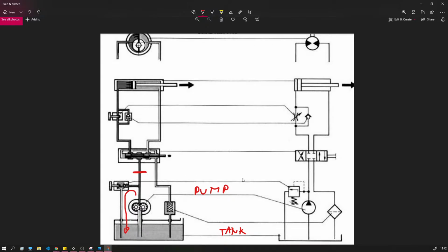So we have the relief valve here. If we have the pump that's giving us enough flow rate, and we have the set relief valve here that's going to set the maximum pressure for our system, we have basically conditioned the oil for use in the system. That's the check valve.